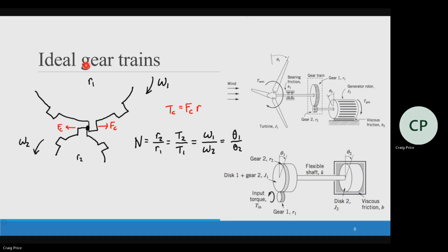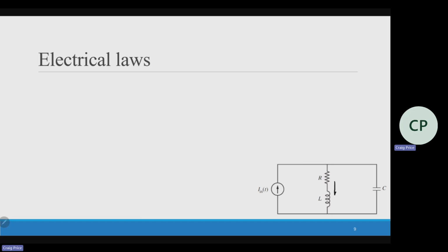We talked about some of the electrical laws. KVL, KCL, those are your starting points in your definitions. On your diagrams, one thing I would really recommend: you have the option of doing all the KVL, KCL, just keeping the circuit as is. You also have the option of impedance. So maybe you combine things and draw a new simplified schematic. You're going to make a drawing either way. Don't forget to draw the currents on here.